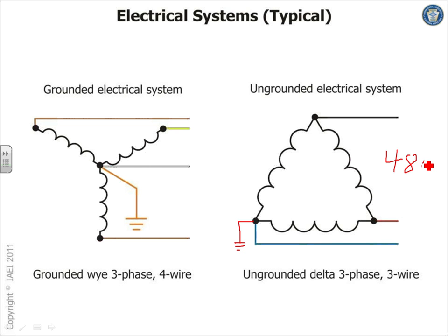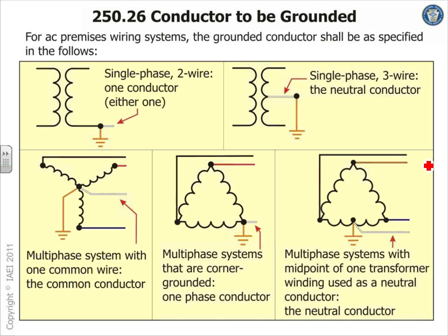So you have a panel, the voltage to ground is 480. How dangerous would that be from a shock hazard point of view? Typically what? 277 is the voltage to ground. You double the voltage to the ground. If you get a shock with a ground fault on a delta system that has a ground fault on it, you're dead. Your chances of surviving a 480 ground fault here is much less than if the voltage was 277. Anyway, so that's why the code wants you to do what? Monitor if you have a ground fault in your system. Not because we care about your process, but because of the shock hazard that comes from a higher voltage to ground.